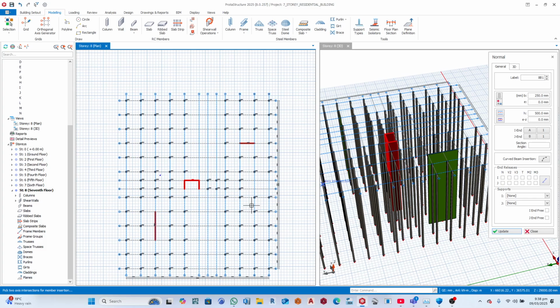I've done the same thing, only that in the way I'm isolating the columns, I'm not repeating the same type of column per axis or per story. I'm taking consideration of the fact that this same type of member, a column of the same size, is repeating for maybe 4 floors. So I don't have to do it on floor number 4, come and do the same again on floor number 3, the same on number 2 and on number 1.